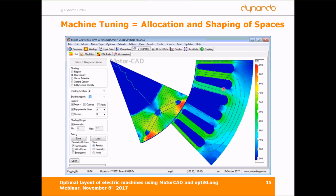Then there are trade-offs in terms of the thermal behavior, and in terms of the forces which excite vibration, noise, vibration, harshness. By choosing the right topology, and then the right angles, thicknesses, and air pockets, you can control the field lines, how the motor generates forces and torque, how efficient it is, and how much losses there are in the iron and the copper.